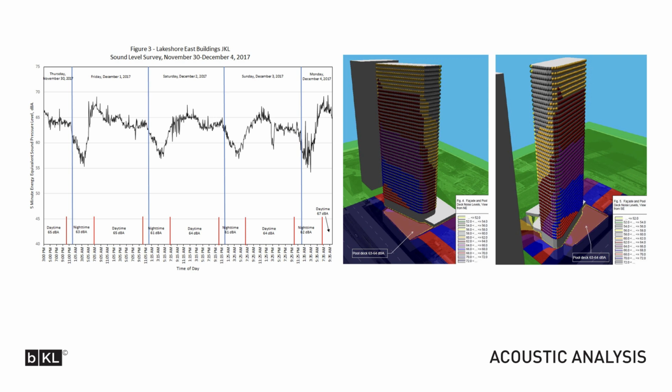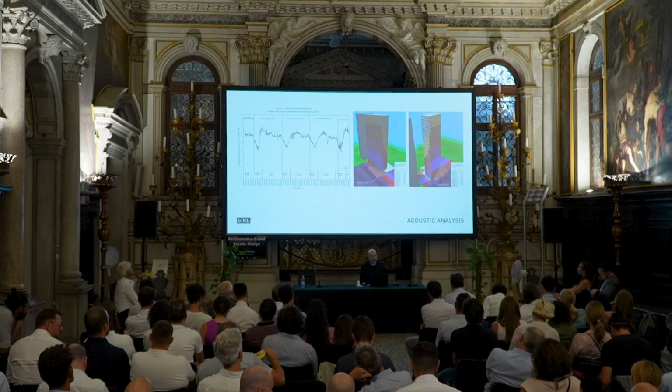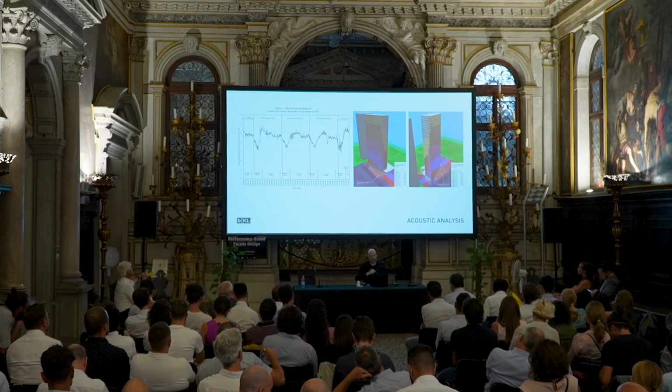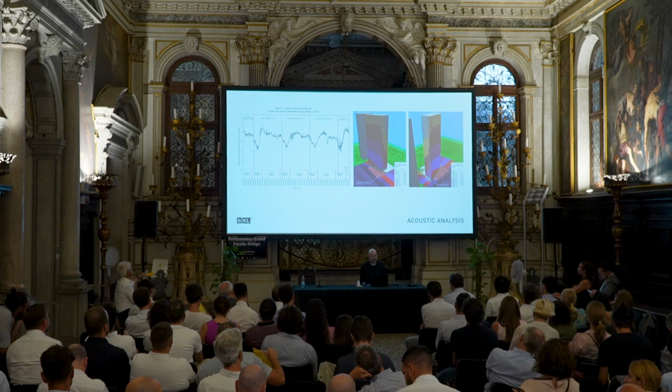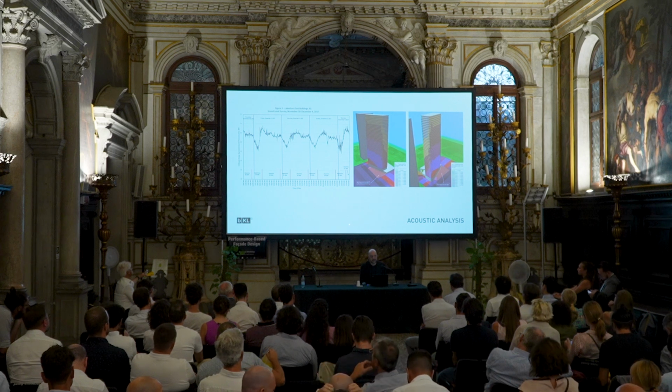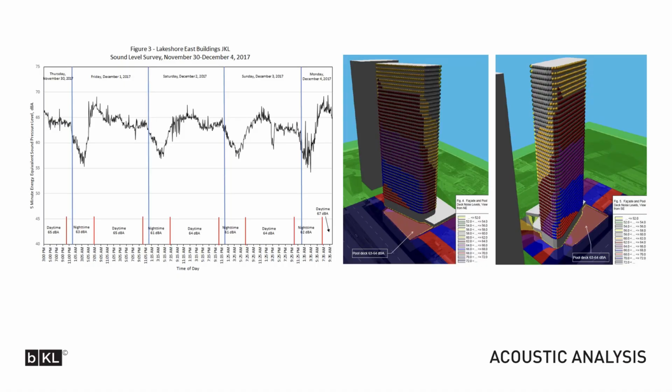Literally took sound testing equipment on a boom arm on a cherry lift to the middle of the site and left it there for a week to look at and understand the daily cycles and weekly cycles of the different noise levels and noise frequencies that are happening at the site.